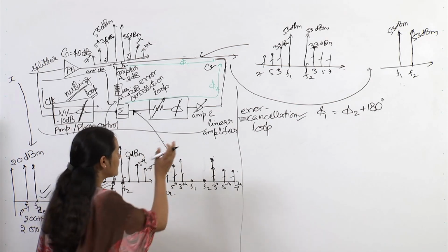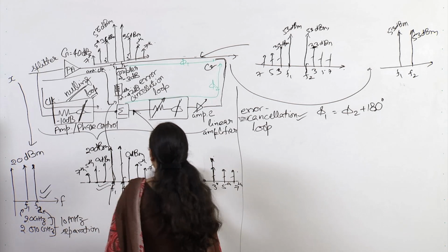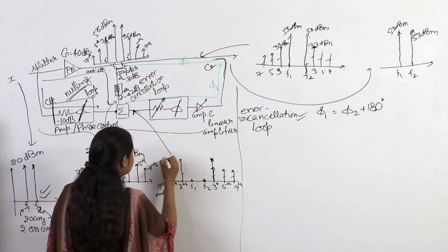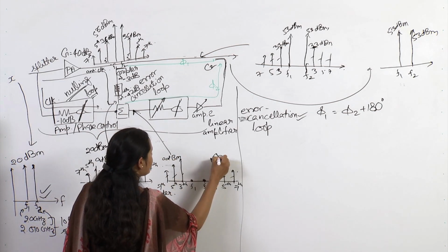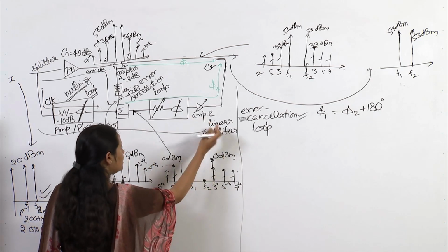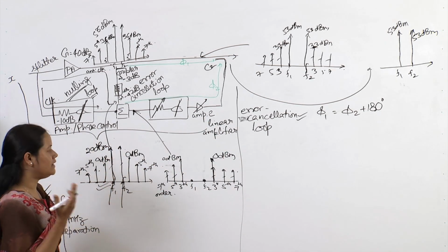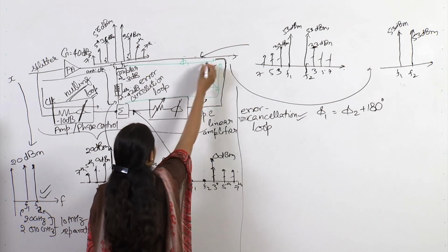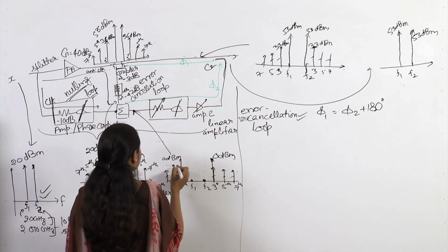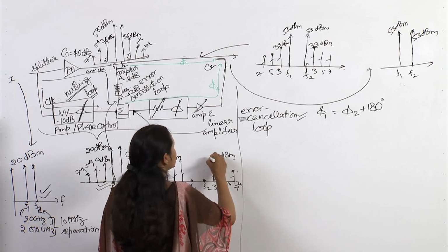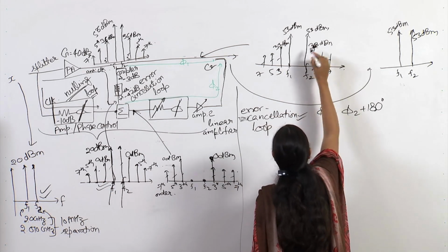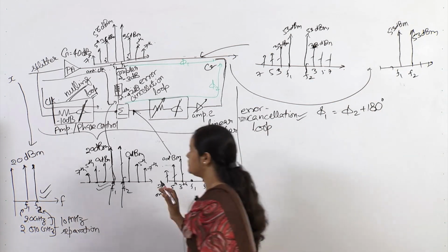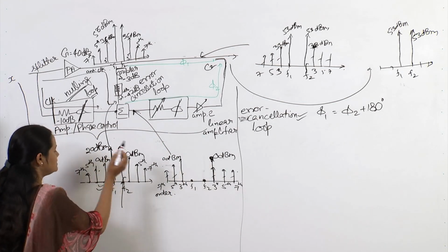What is the positive point? This amplifier has to amplify IMDs which are much lower, almost 20 dB below the main power level. So, it was around 0 dBm here. So, we can use a low power amplifier here, and we can easily keep it in the linear region of the power amplifier. By doing so we will match the gain of this path, and again the power of these components should be equal to the power of these IMD components, so that the perfect cancellation will happen, and we will get our actual signal output. So, this is the feed forward system.